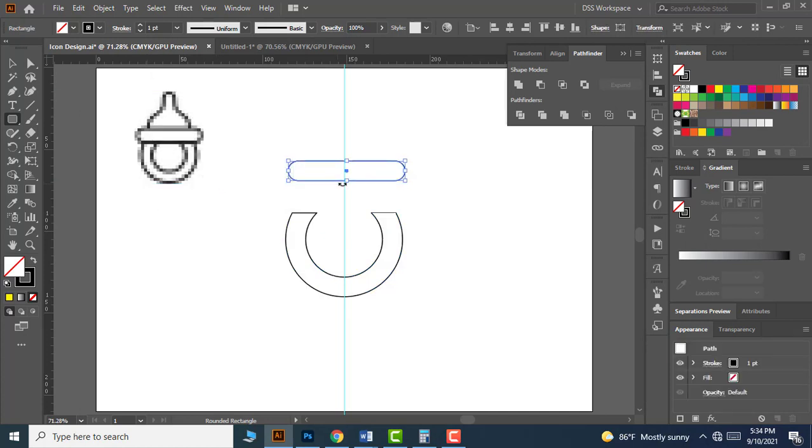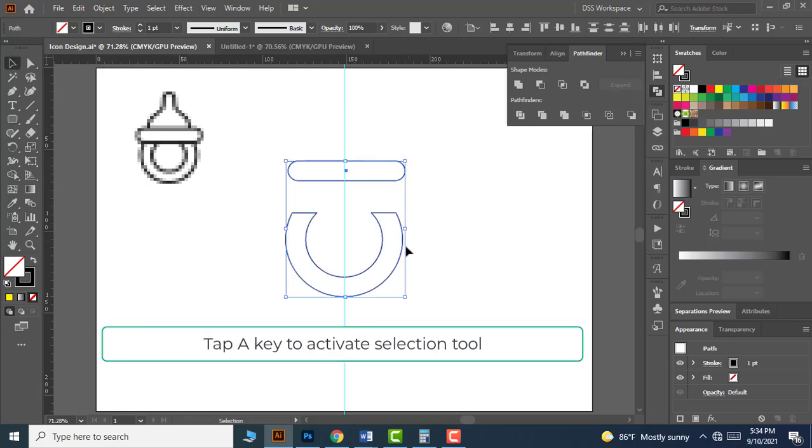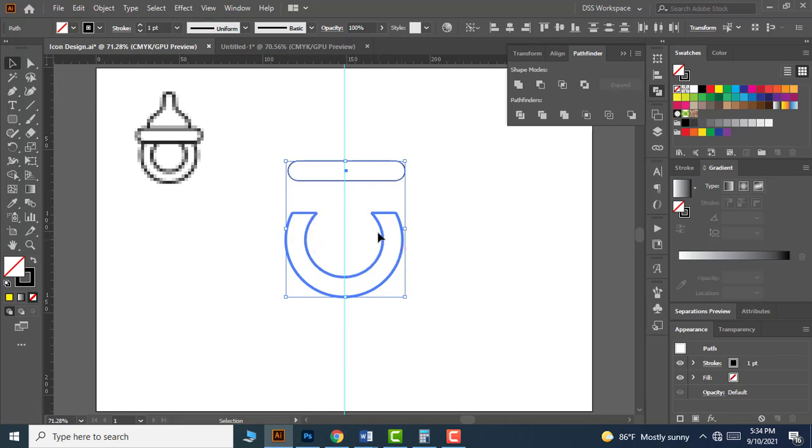and then click OK. Then select both objects and click the circle object again to activate it as a key element. Once it's activated as a key element, you can see the selection border is thicker than the other one. Now I am going to center align this rectangle object with this circle object.